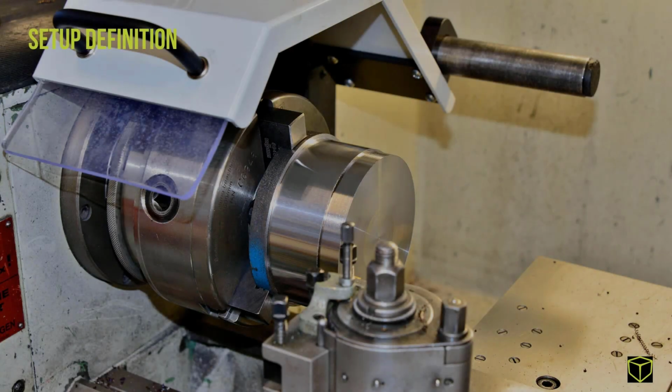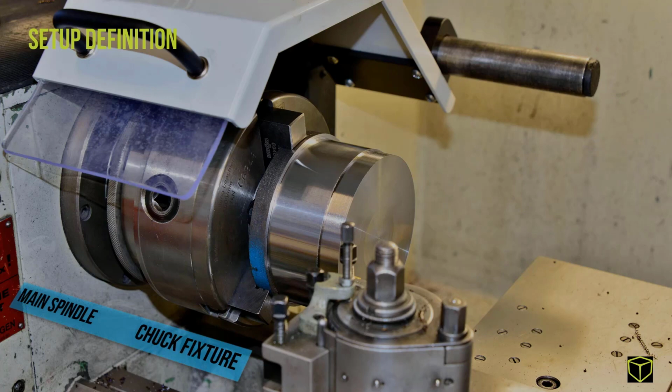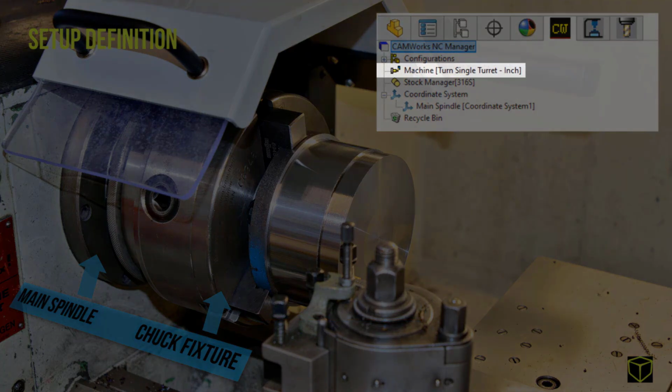For those of you who are unfamiliar with two-axis turning or parts frantically spinning sideways, I'd like to take a moment to discuss the importance of understanding the following information that's related to this picture. Safety being number one is a given, but I also want to minimize any frustrations using SOLIDWORKS CAM Professional and CAMWorks. The left side of this picture shows the main spindle and the chuck fixture, which is holding the round stock. This is known as a rear turret or single turret machine configuration.